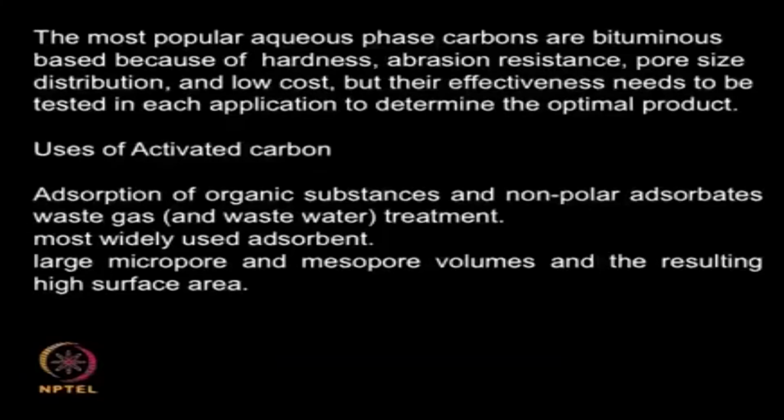So the most popular aqueous phase carbons are bituminous based, because they are very hard, they have very good abrasion resistance, good pore size distribution, low cost, and they can be used for a large number of applications like organic substances, non-polar adsorbates, waste gas treatments as an adsorbent and so on. That is why it has got very good applications in several manufacturing processes. Okay.